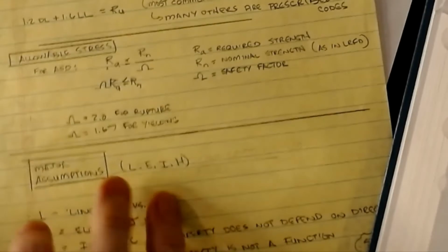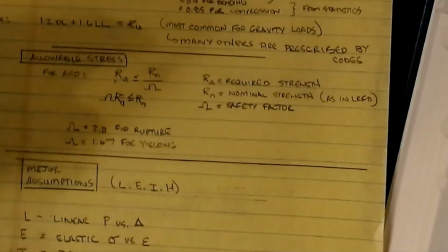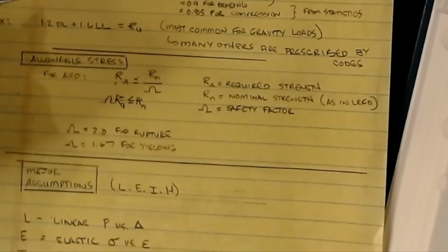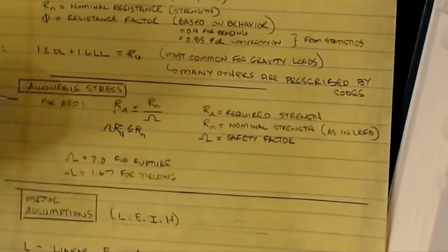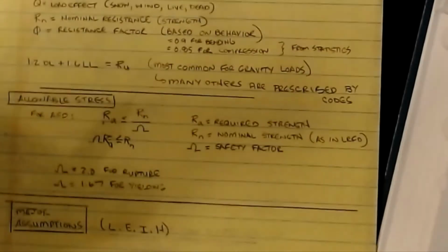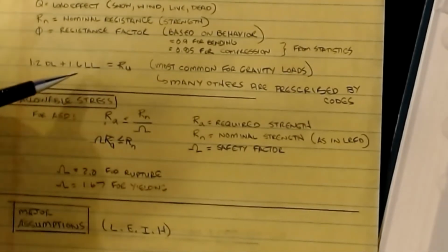What happens with LRFD and ASD is that the reason it came about was that they started doing statistical studies of sizes of members when they were developing the methodology, and they found that, generally speaking, the results from an allowable stress member versus a load and resistance factor member are comparable. You might be one size different, and allowable stress was typically just a hair heavier. Not always, but a lot of times they give you the same member selection in design. But it was a way to get a little bit of economic savings if we were willing to do the extra work to split out the dead load and the live load separately.